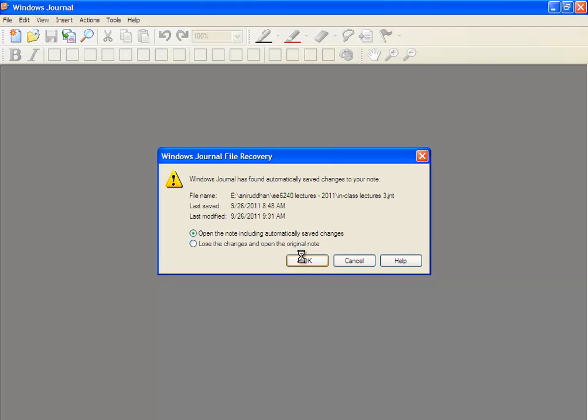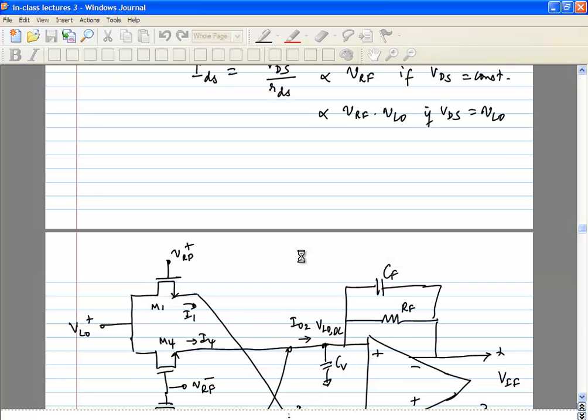Typically, most of the gain comes from the baseband. What do you have in the RF? You have the LNA, you have the mixer. The signal coming in is 1 microvolt. The signal is probably a few hundred microvolts coming out of the mixer, and at that point you are adding all the input referred offset of the baseband. That will typically be in millivolts or tens of millivolts. That is a big problem because your offset is going to be much larger than your signal at that point.